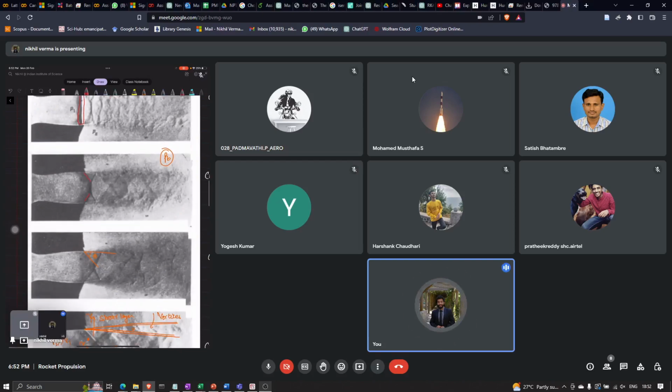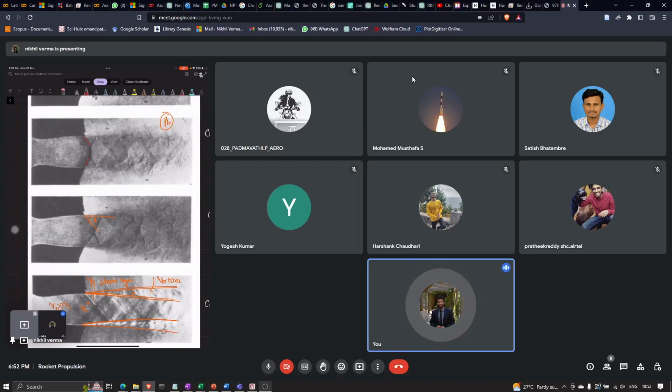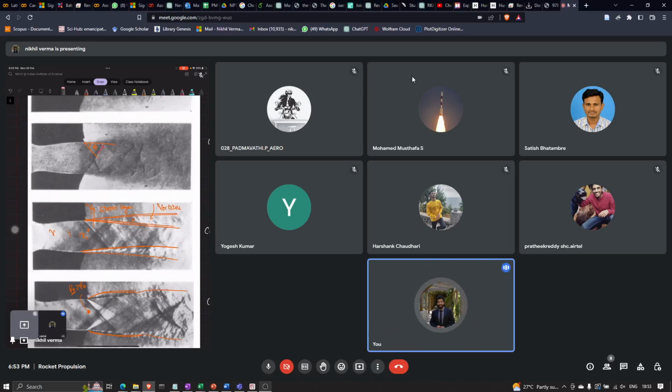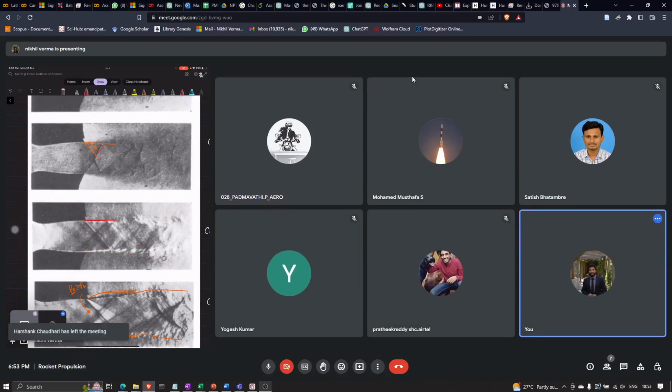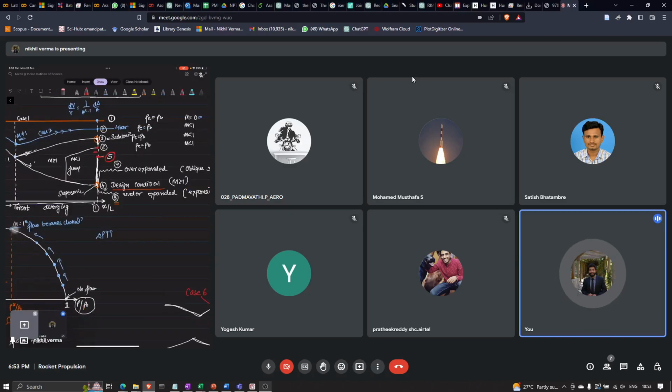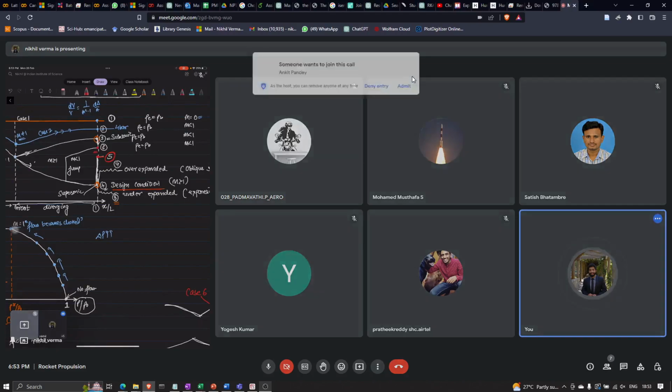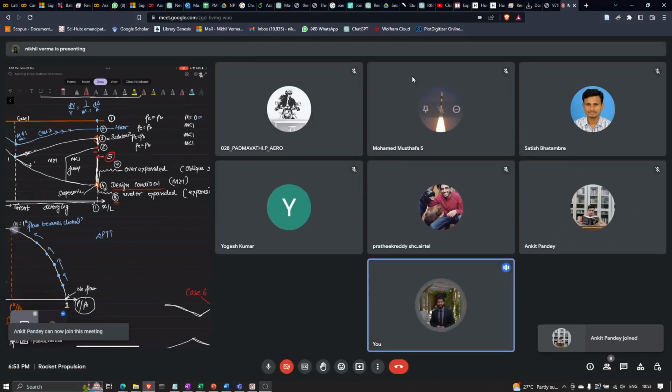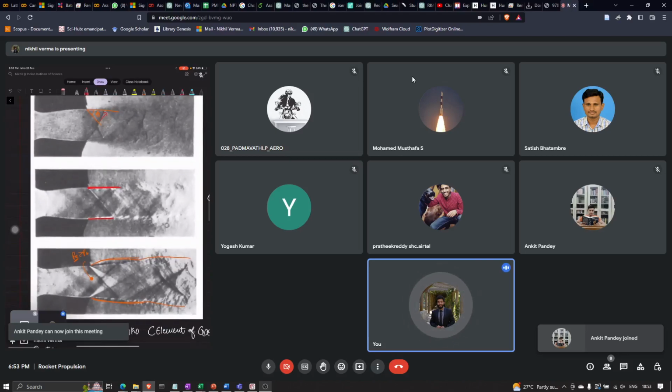As you further decrease the pressure, if this is theta, the shock angle will reduce, and at a certain pressure the shock angle will become zero. This corresponds to the design condition for the supersonic nozzle. You will get fully expanded flow, where you do not have a shock.